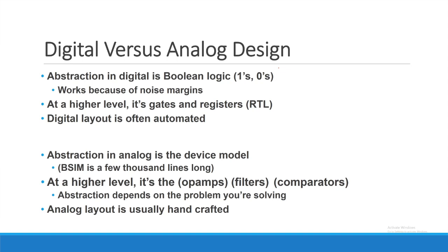So just to wrap this up from the discussion about digital versus analog and why we're even here in this class. In digital, the key thing was that I could abstract things as being ones and zeros. The reason I did that was so that, for stuff that varies around the actual analog level, I'm just going to ignore that. That lets me say that I have a noise margin, lets me build things up and pretend that there was no noise in the system.